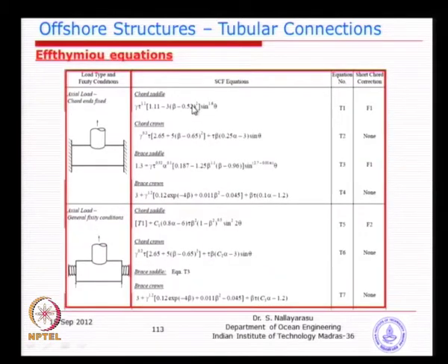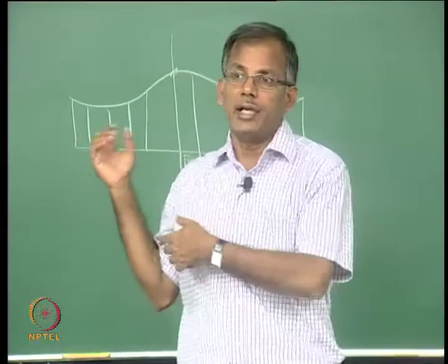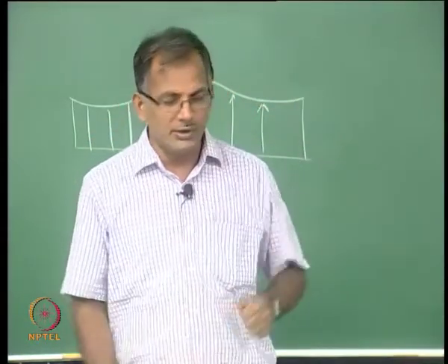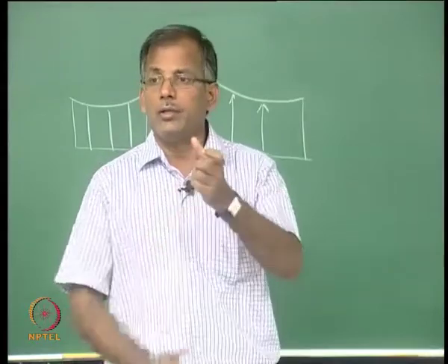So, like this the whole set of 4 types of joints, 8 types of loading. See here axial load, and then the same T joint, instead of fixed at both ends, has spring supported ends. That means this is going to be more realistic. If you look at the jacket, yesterday we were trying to draw one picture, you will never get 100% fixity like this, because they are also connected to another member.